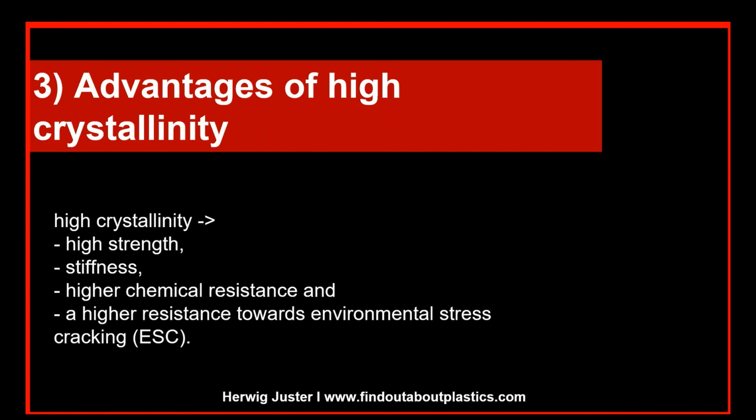And when you think of polyamides, there we always have the water uptake issue, which mainly occurs in the amorphous region. So when it is possible to achieve high crystallinity, the amorphous regions are smaller, which lowers the possibilities to take water up. And as a result, the part dimensions will be kept more accurate.